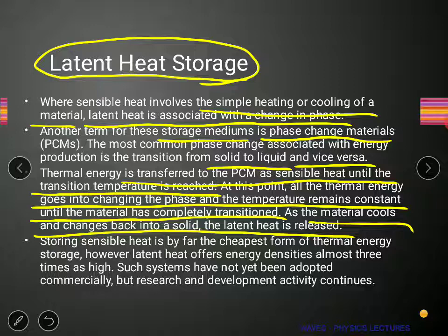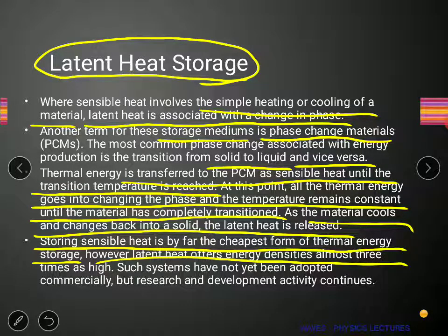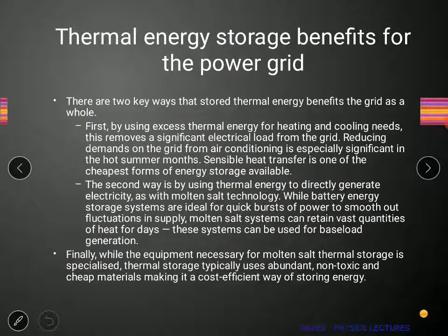Now this is actually a costly affair, because sensible heat is far cheaper from the thermal energy storage. However, latent heat offers an energy density almost 3 times as high. That means the amount of heat that a sensible heat storage system can store is 3 times lesser compared to latent heat storage. So latent heat storage can store more heat, but this kind of system has not yet been adopted commercially, and research and development is still in progress.